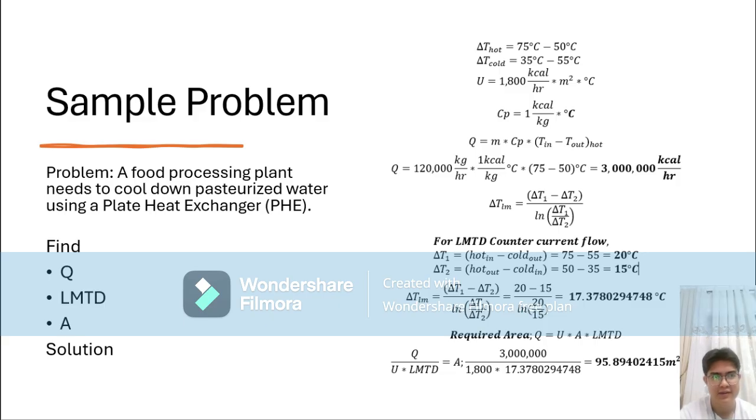Although that is a substantial area, the benefit of a plate heat exchanger is that by stacking together multiple thin plates, this kind of area is achievable with a small volume heat exchanger, because heat transfer depends primarily on surface area, and an increase in thickness of a material increases thermal resistance.